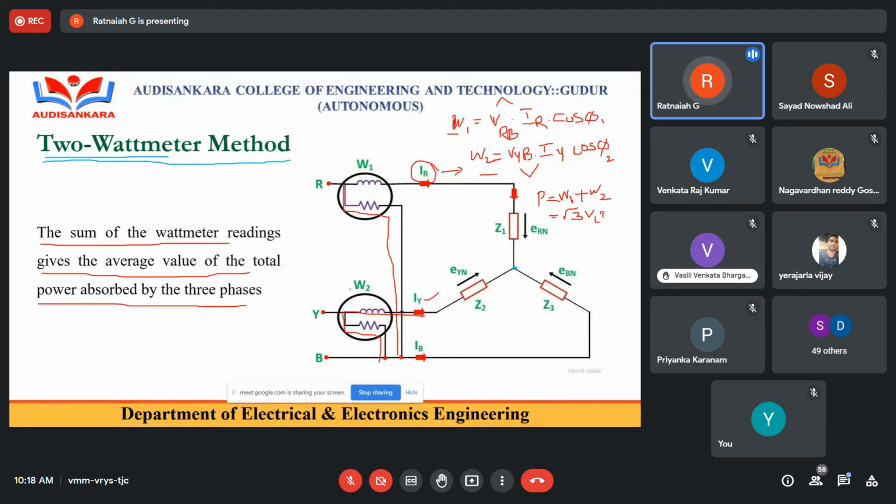So with the two wattmeters, how can you know this relationship? That I can explain. Generally in the 2 wattmeter method, if we add W1 and W2 we get the total reading. That reading must be equal to the general power equation, that is root 3 times VL IL cos phi. How to achieve this relationship? That I can explain with the phasor diagram. There you can understand how it is possible. Okay?